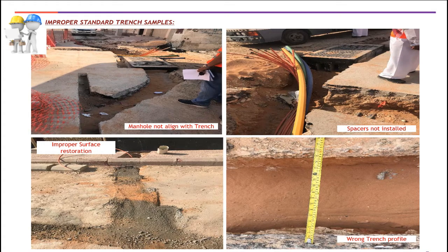If you notice the picture on the upper left, there is an existing cable beside the trench, preventing the two cover handhole to be installed along the trench. This resulted in a disaster just because the team didn't perform ground scanning and a test pit before executing the trench.